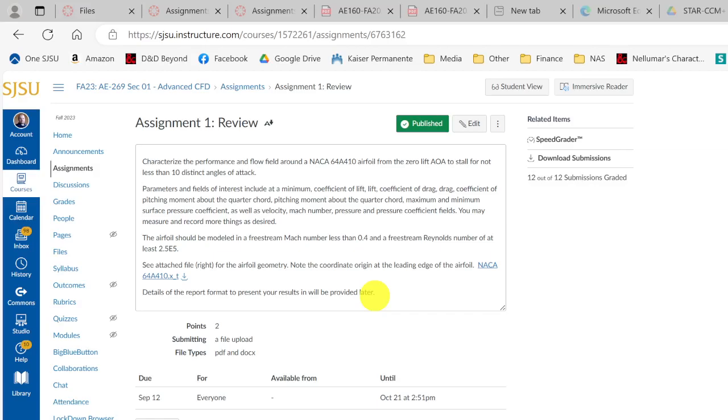So it's a two-pronged thing. The first part is that you had a lot more cells because you needed to get cells into a small gap, which is only natural. If you have a really small gap and you need 3 cells in it, each cell needs to be that small, which gives you lots of them. So it takes longer to do an iteration because you have lots of cells. The other side is that because you have lots of cells, there are lots of interactions between them, so it takes more iterations to converge.